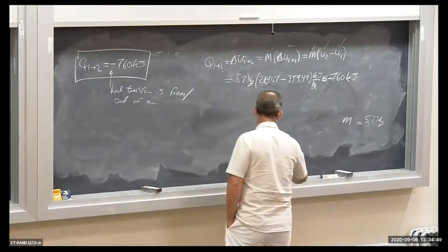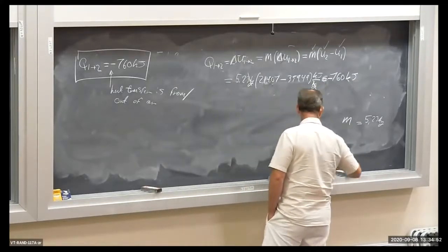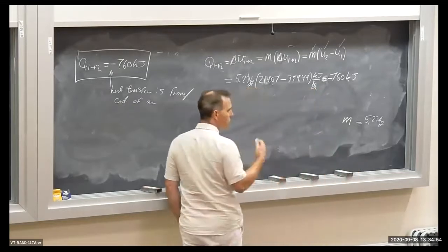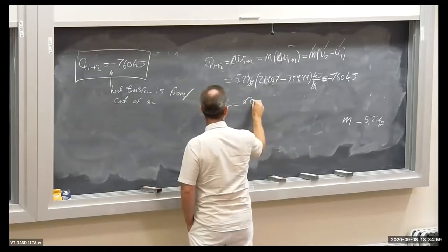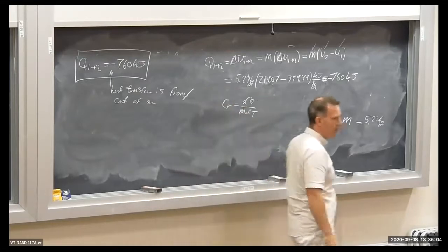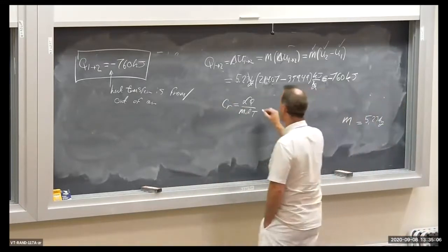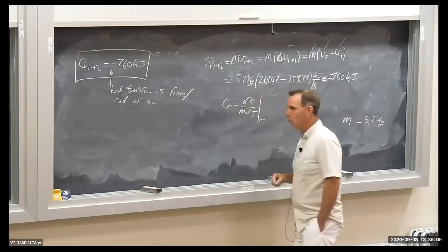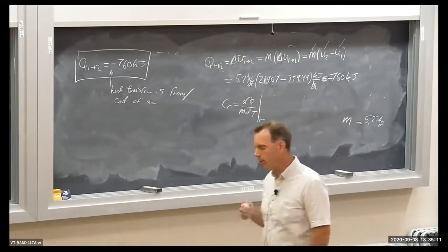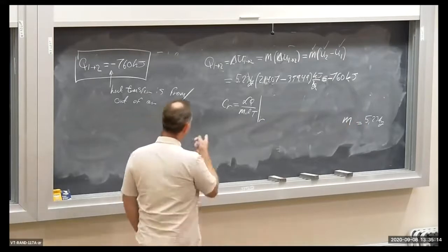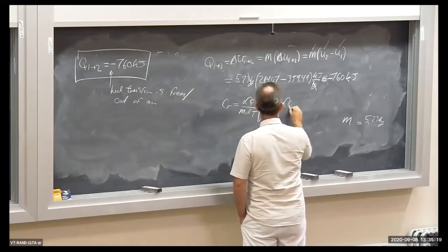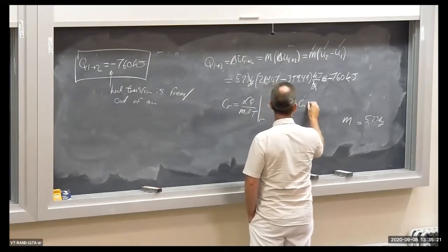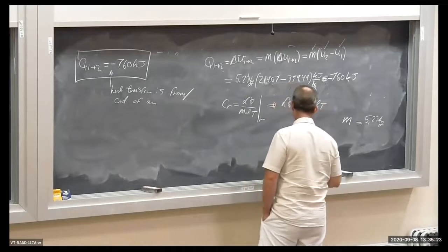So let's not apply the energy balance, but let's use specific heats. So recall, Cv is equal to delta Q over m dT. That's the definition of specific heat at constant volume. We have a constant volume process going on here. It's in a rigid container. So I can solve this for delta Q. Delta Q is equal to Cv m dT.